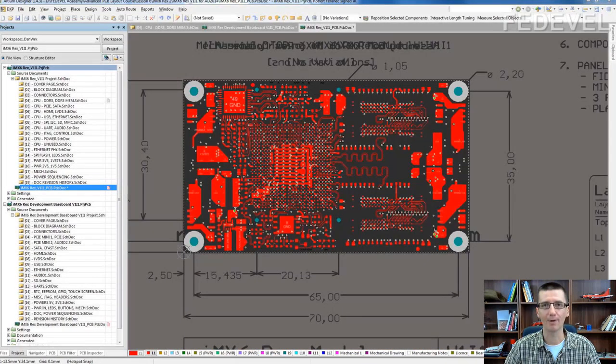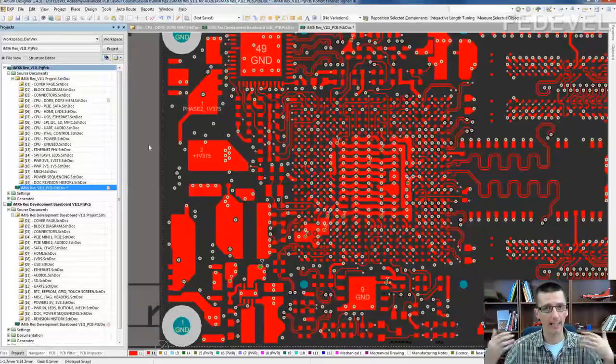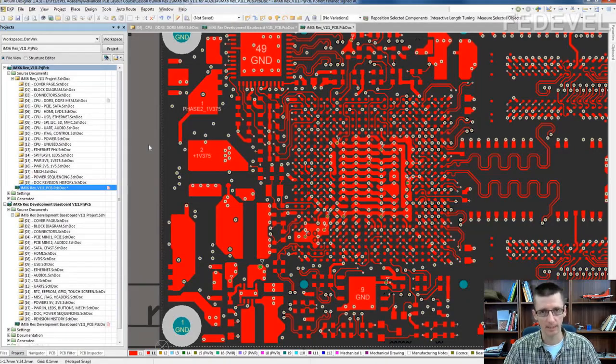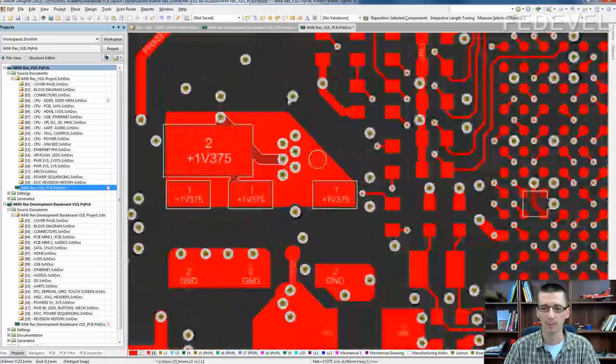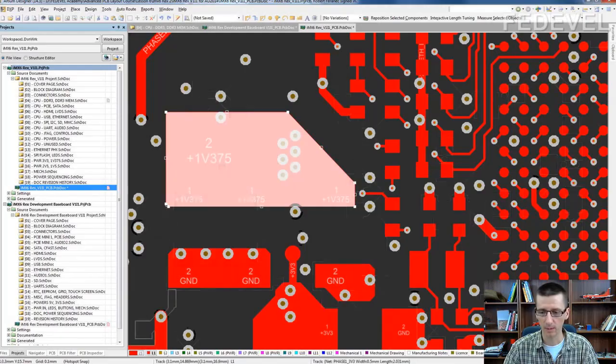Before we finish, couple of tips. If in your design you have some polygons where very high currents will flow through, then you can, for example, increase the copper thickness, we were speaking about it, or you can use multiple layers for the polygon. For example, you can go and copy and paste this polygon also on other layers. Select the polygon, Ctrl C, go on layer 2.